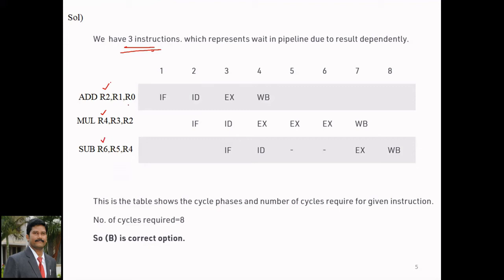So if you observe, after execution the result R2 is needed by the next instruction. After execution only is the result R2 available, and then only can it execute this second operation. This is data dependency. Okay, the instruction I2 depends upon the instruction I1, because after executing it, only then is the R2 value available, the result, and that value needs to be taken by the next instruction.